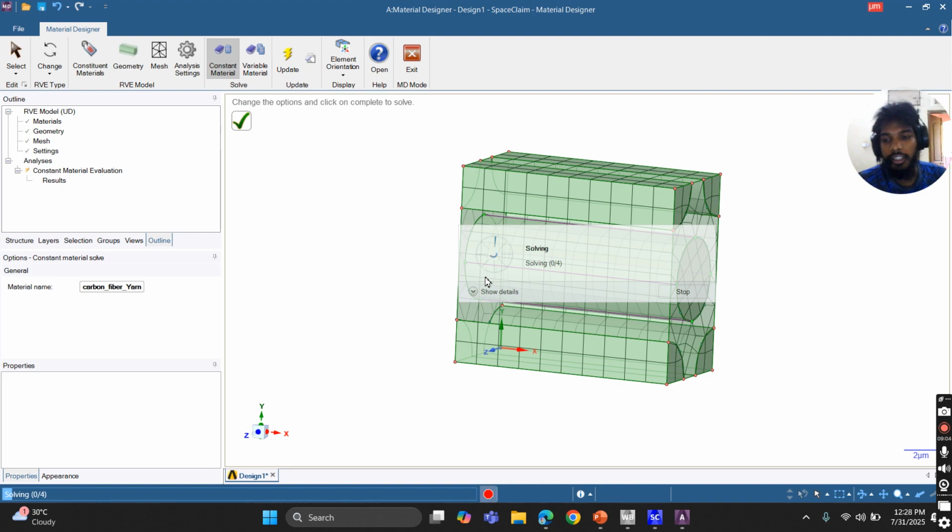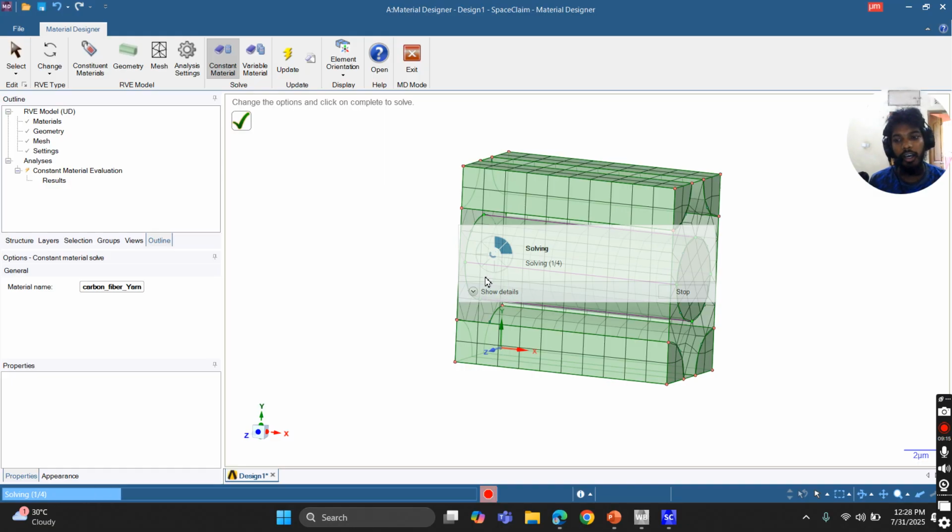In woven composite, there are four important parameters influencing our strength, stiffness and elastic properties. These four properties are called fiber volume fraction, yarn fiber volume fraction, fabric thickness and yarn spacing. These four parameters are the most promising to influence the elastic properties of a woven composite. So you need to evaluate the effect of these four parameters.